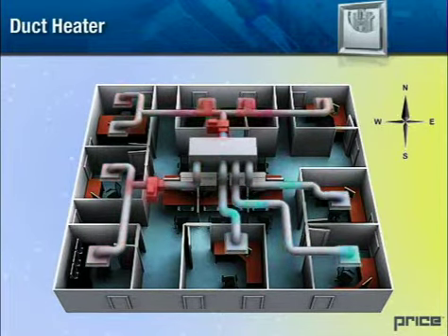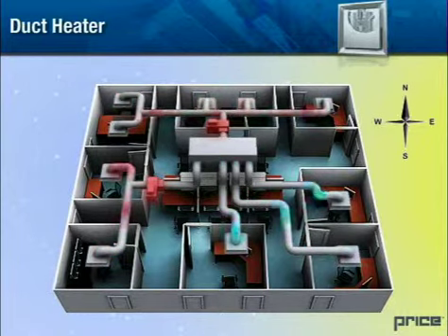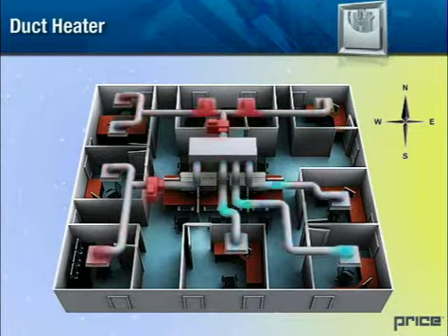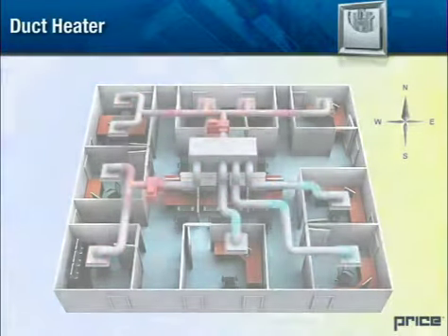The zones in which the VAV diffusers are within will automatically switch to heating mode if the option is selected, ensuring that there is adequate zone ventilation for each specific zone demand and allow the other zones to continue to function in cooling mode. A major drawback for duct heater station design is the additional energy costs required to cool, then reheat the air.